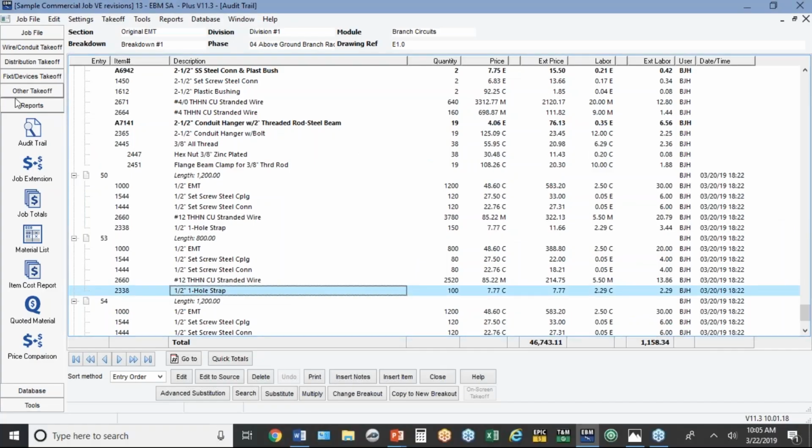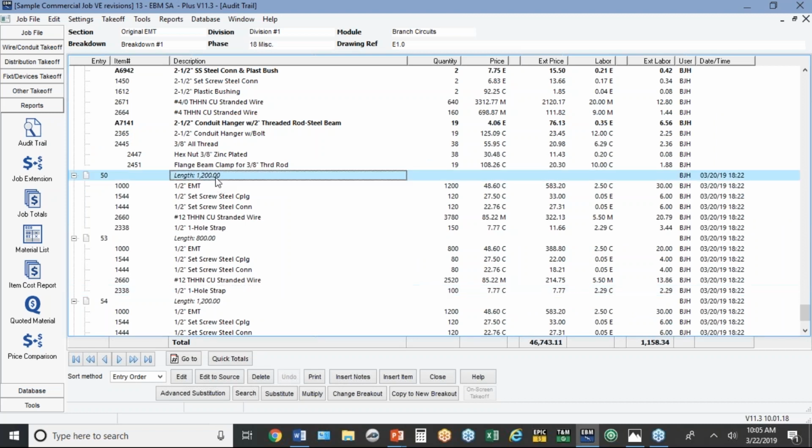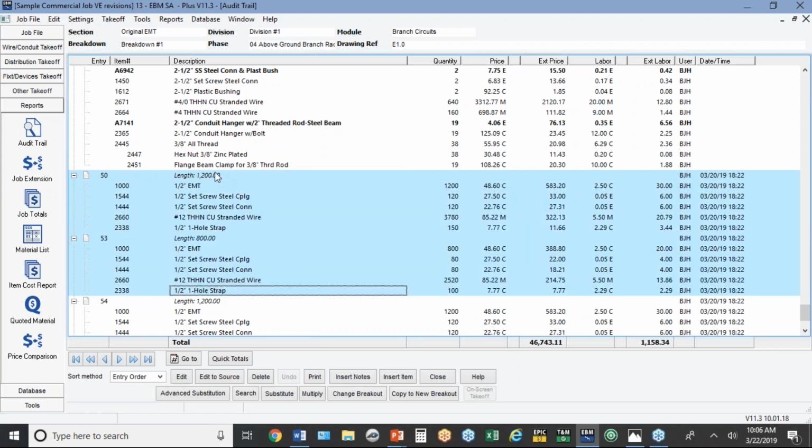There we go. Okay, so what I've done here to prepare for this webinar is I've taken a couple of entries. You'll see my audit trail here where I put in 12. I don't need to turn my mic on, do I? Nope. Okay, sorry about that. I've made a couple of entries with half-inch EMT with 3 number 12 wires. You'll see these two entries that I just highlighted, one with 1,200 feet and one with 800 feet.